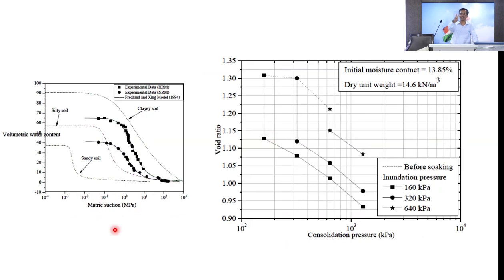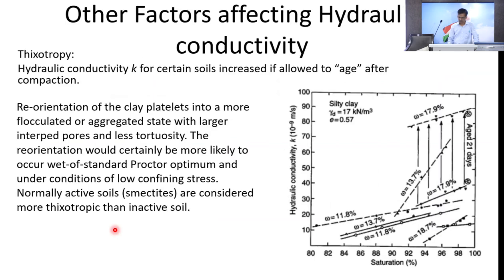That means you said 20%, 30% water is there, so it is not saturated. Terzaghi said consolidation is valid only for saturated soil. So how can I apply that in this case? Maybe the void ratio or settlement I am calculating using the simple formula given by Terzaghi may not be valid. So this is another aspect.